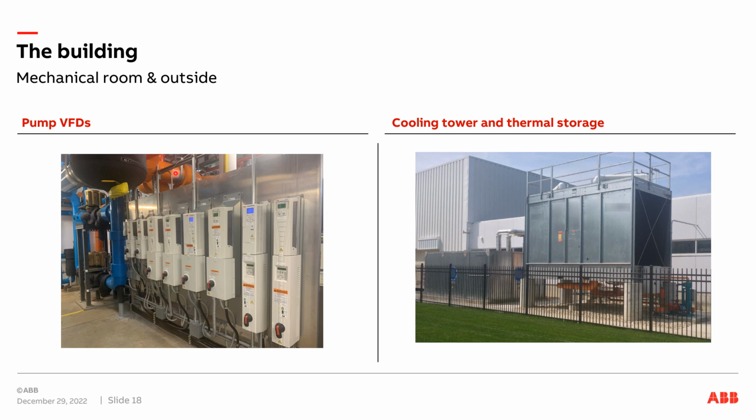I got that orange piping up there. That tells me it's my condenser water. There's also some red piping up there. That's going to be my hot water. I can just barely see it right there where the condenser water goes into my hot water system.